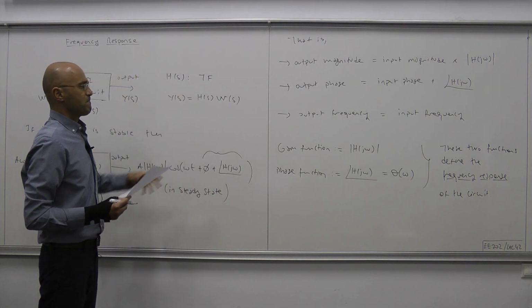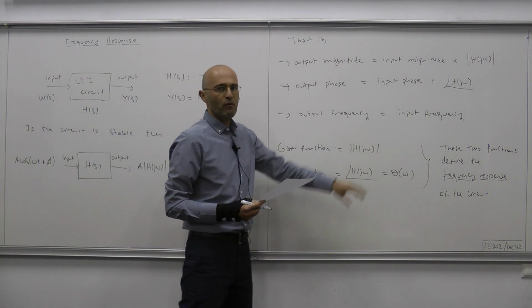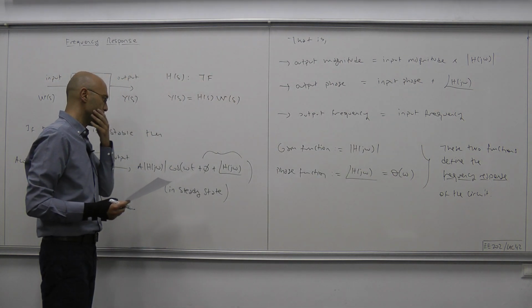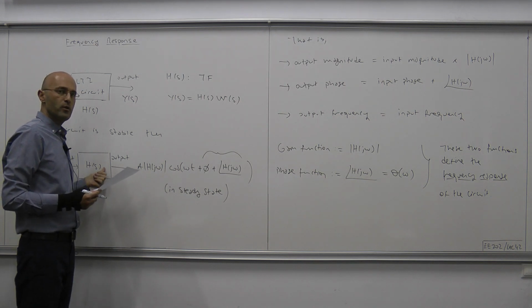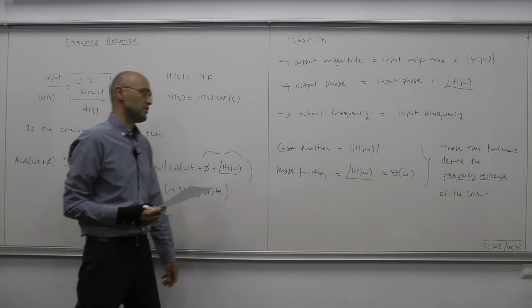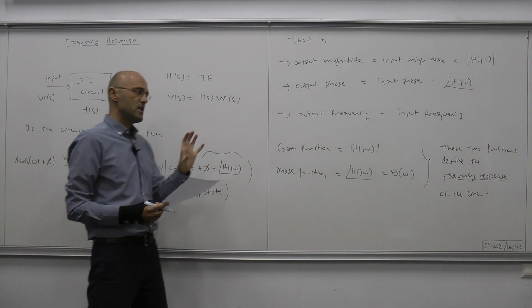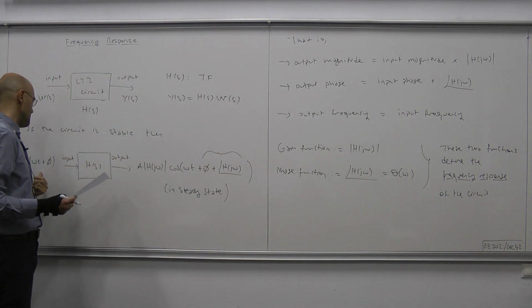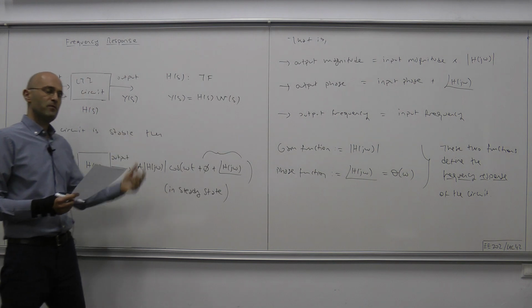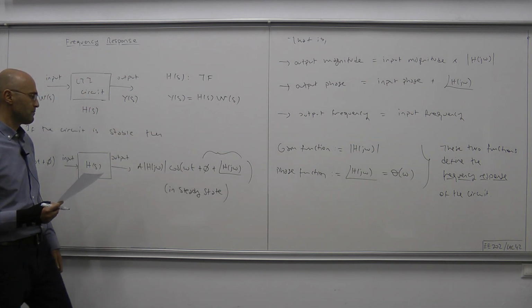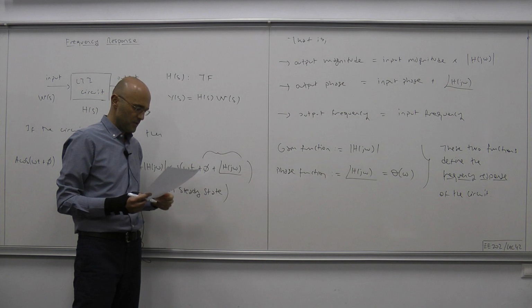Okay, so together, if you know both of those functions, which we can compute provided that we have access to the transfer function, together they completely characterize the relation between the input and output when the input is a sinusoidal function, in steady state.